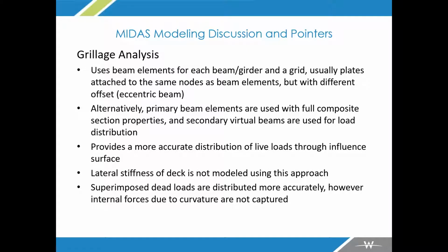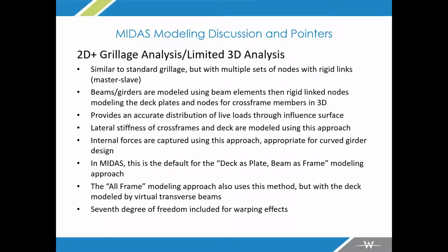Grillage analysis, like I described, you've got beam elements offset with plates, and you're capturing your lateral stiffness. I went over all that, and then the 3D analysis, which is the full amount. Now in MIDAS, you're going to see this as deck as plate, beam as frame. That's going to be your 2D plus for what you select there. And again, that's those plate elements offset with the beam. The all frame is going to be your full 3D.